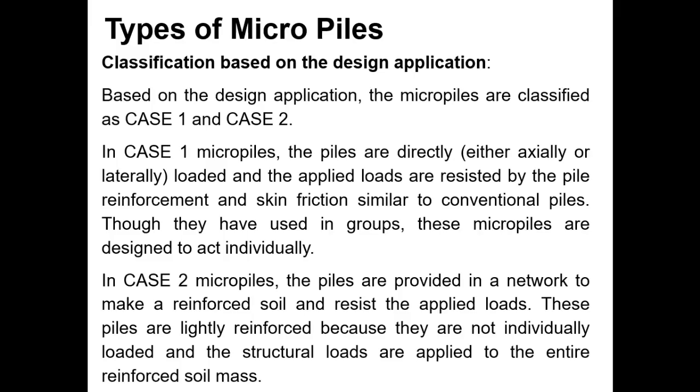In case 1 micropiles, the piles are directly loaded and the applied loads are resisted by the pile reinforcement and skin friction, similar to conventional piles. Though they are used in groups, these micropiles are designed to act individually.